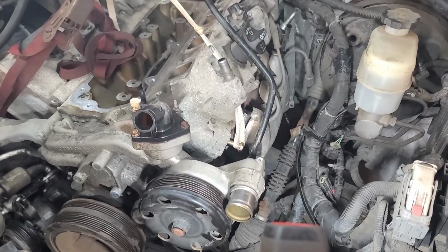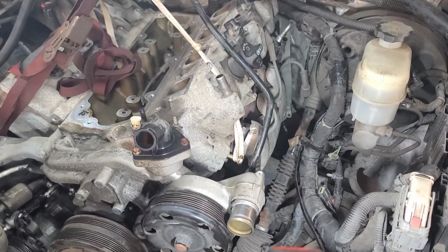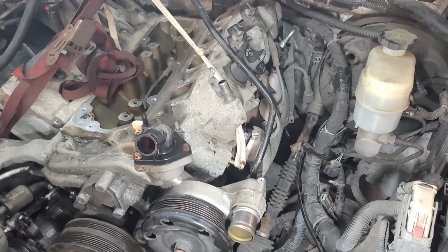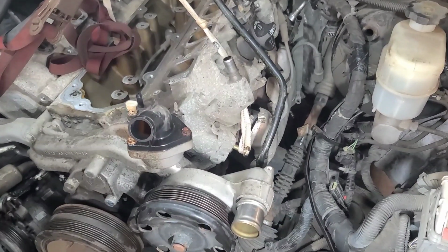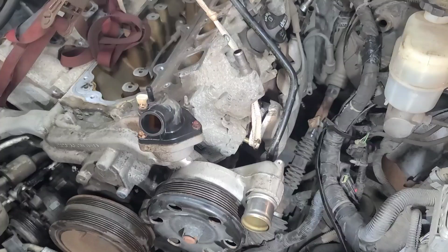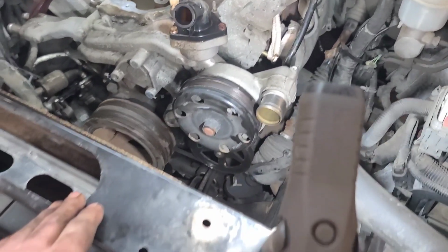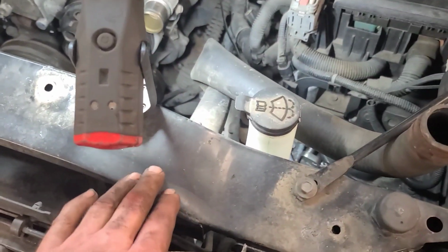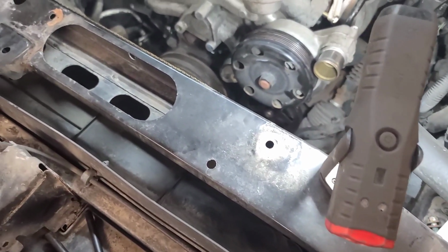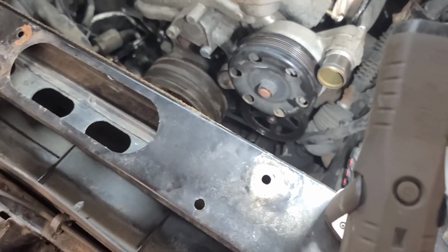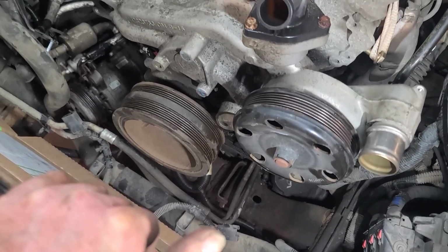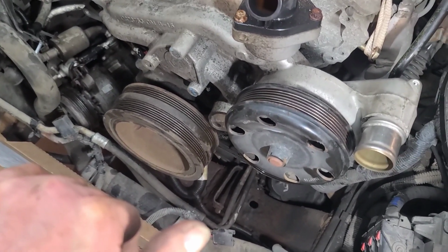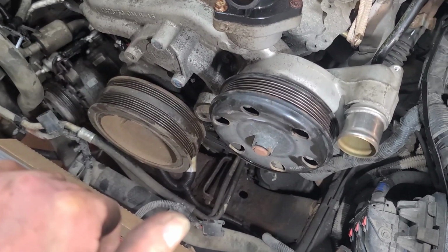I had to use an air chisel on the dowels on the bell housing liners, because they wouldn't come out of the transmission. I got it separated and lifted, but it won't come out through the top here because it's too big. And General Motors, in their infinite wisdom, didn't make this cradle or rad support removable. It's welded in place here. So I've got the cover off. I'm going to take the harmonic balancer off and the water pump housing off, and hopefully that'll give me enough room to get this thing out of here.